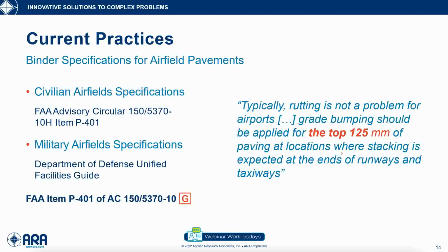That's for highways. For airfields, there are specifications for civilian airfields that are set by the FAA, particularly for asphalt mixtures. In the circulars, we look at item P401 for asphalt mixtures. For military airfield specs, the DoD sets these specifications.